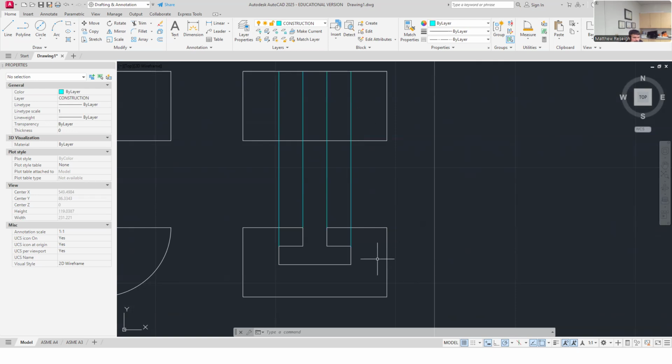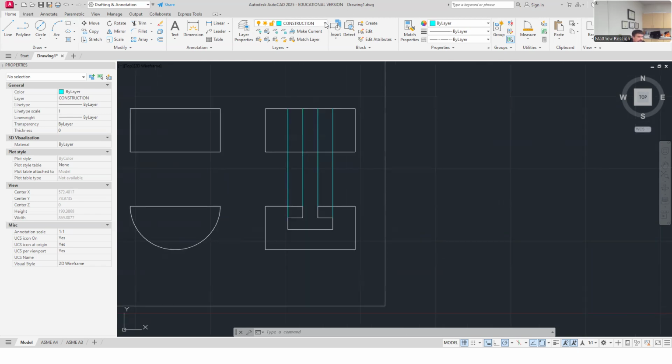That's where these lines that represent a surface would appear as a surface in the right side view. If I truly took a right side view, they would appear as a surface that's hidden. If I took a cutting plane line and cut that in half and, instead of drawing a right side view and having to show hidden line work, actually expose and decide to cut through something and establish a cutting plane line, then I can expose surfaces as visible lines. And sometimes I have to do that. So sometimes surfaces are buried, sometimes surfaces appear as lines, sometimes they appear as hidden surfaces that I may need to expose. And anyway, just a thought process I want to think through a little bit.